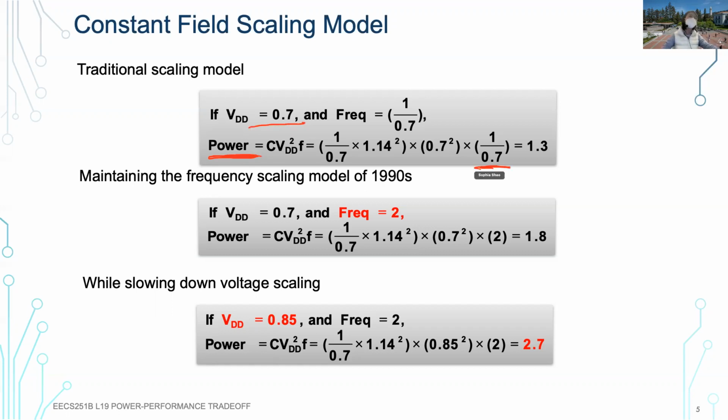From F, frequency is higher, right? Our transistor is smaller, we can actually switch faster, so frequency is higher. Voltage is actually lower, right? Because we're at lower voltage here, we can also get lower voltage. And it's very important, we'll come back to this. Voltage has a quadratic relationship, especially with energy. So that's very important. And the capacitance is also getting smaller, right?